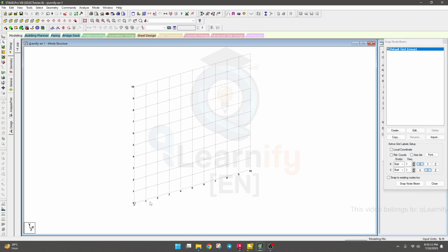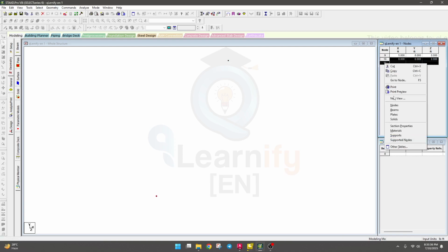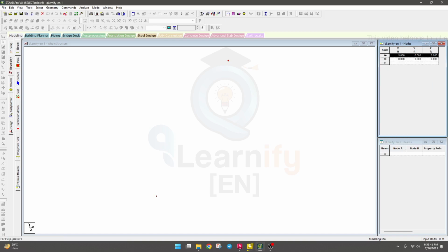Now to draw node, actually I'll not create node with respect to this line, because this line is a random reference line. So I'll use this option, click geometry. In geometry you can see here 2 points are available. Maybe for your case you will not get any point here. So I will take it 0 0. And here I'll delete them. Actually no need. I will start from 1. Yeah, from here we'll start from 1. It will be better.